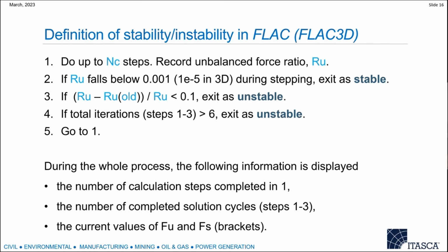Here we talk specifically about how stable and unstable are determined in FLAC. First, we run up to n characteristic steps and record the unbalanced force ratio, RU.